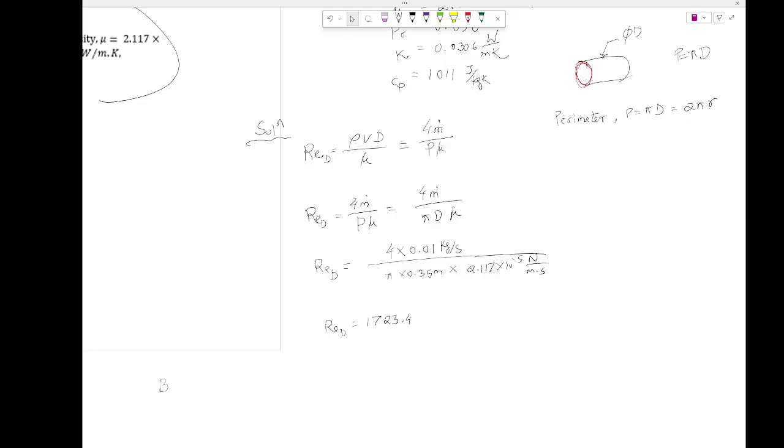So you should be writing, okay, so we have this thing is less than Re_D,c. Now, what is this? This is the critical Reynolds number. And we know the critical Reynolds number is either 2300 or sometimes people use 3000, right? This is Incropera. This is Cengel. Two books give two different values. I did talk about it. All right, so we know this is laminar flow.